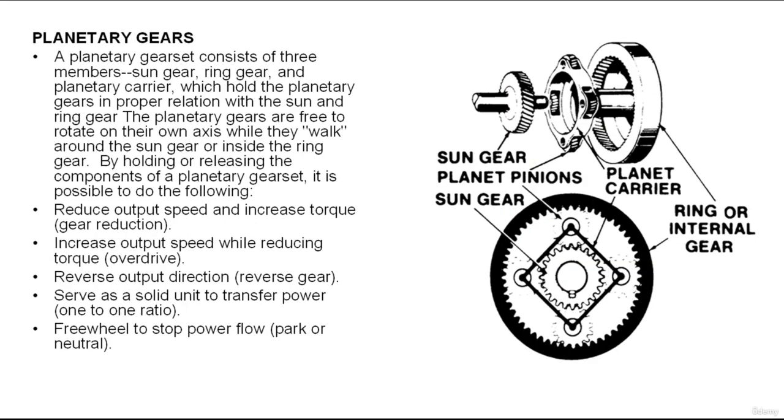And let's move right now to planetary gears. Nearly all automatic transmissions rely on planetary gear sets to transfer power and multiply engine torque to the drive axle. Compound gear sets combine two simple planetary gear sets so load can be spread over a greater number of teeth for strength and also to obtain the largest number of gear ratios possible in a compact area.